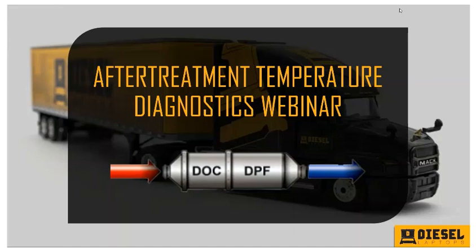So when I run a forced regeneration, I'm doing that with the assumption that I'm going to diagnose it. And if you watch a regeneration take place live and you pay attention to the temperatures, you can almost diagnose what's wrong with that after treatment system just by doing that, right, without lifting a single wrench. So I'm going to explain some of that to y'all today, hoping that you can retain some of that and put it to work, be a little more efficient, make a little more money, happy customers, happy boss, happy life.